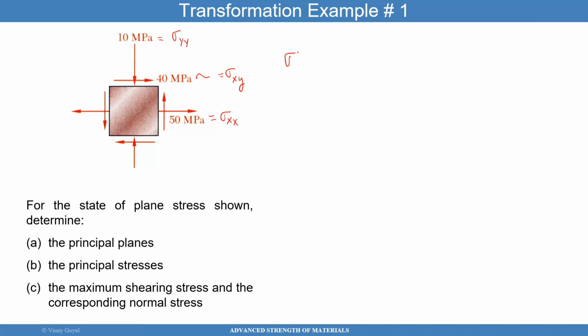So then you put your stress state like this, sigma xx, sigma yy, but it's negative because it's against the surface. And then you have 40 and 40 for sigma xy. That's your stress state, and you can turn this into an eigenvalue problem, like I had shown earlier.